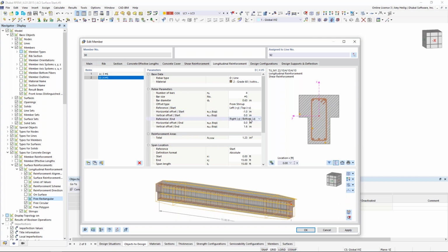This should be right -Y, which we see here, but top positive Z. We want to go ahead and modify this one to a distance of 1 and 0. And if we expand here on the distance to get maybe a larger effective width for our flanges, this will make a little bit more sense as we see our reinforcement on top. So definitely have to play around with this in order to possibly get those offsets correct with the display options. This will also be applied along the full length of the member here.